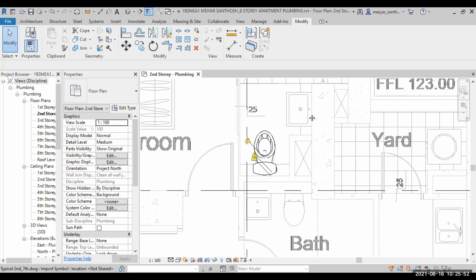But because your hot water, cold water, normally in Singapore, sometimes need not be connected to the rear. You can connect to here and here. But you can see mostly theirs is connected to the wall. You get what I mean? Singapore piping normally is at the surface here and here. So a lot of libraries you can actually configure and modify to suit locally.